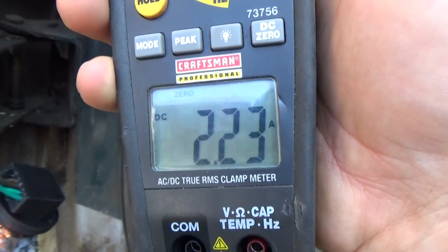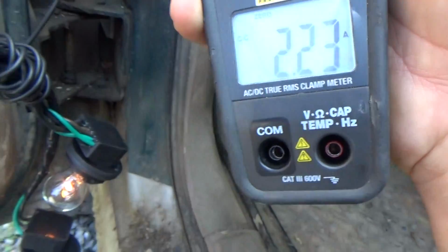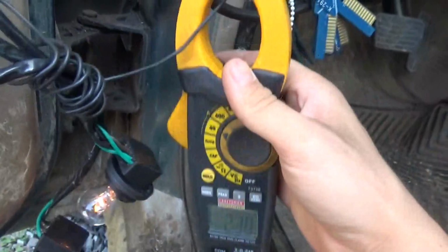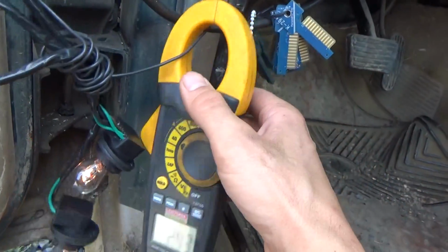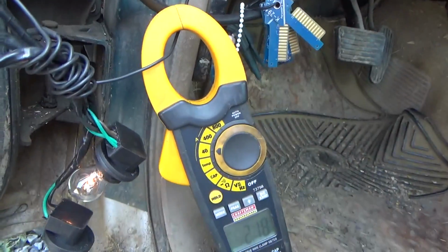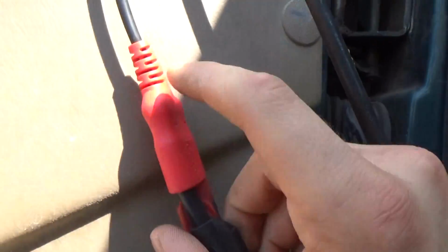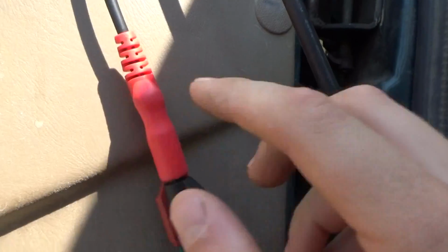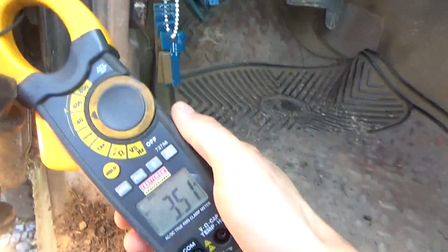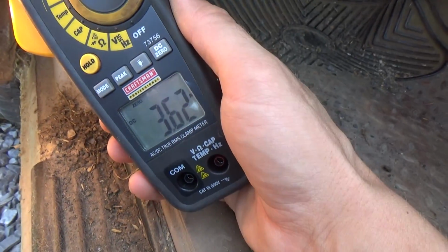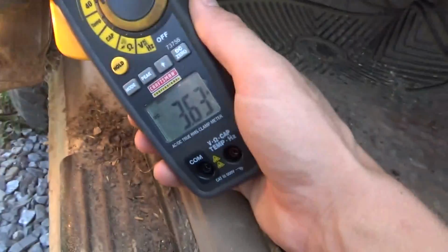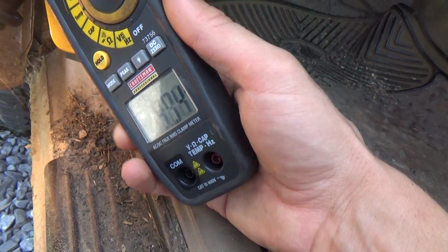So if this is a direct short to ground, the test lights will light a lot brighter. We can actually just do a really quick check. Instead of going to the fuse box, we can just connect it straight to negative right here. This is the really handy thing about having this power and ground. And look, it's about 3.5 amps going through both bulbs. So twice as much current, almost 4 amps.